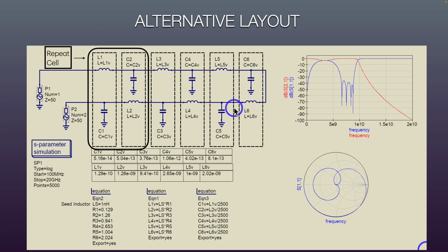And an alternative way to draw that, which some people might find more intuitive, is this horizontal approach, where you have a unit cell with an L and a C at opposite ends of the network, and then a C and an L inside of that. That can just be copied multiple times for however many resonances you want, and you can do a half unit cell as well. So just delete the last section and short it out if you want fewer than a multiple of 2 sections.